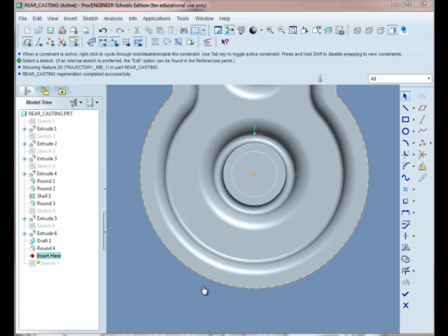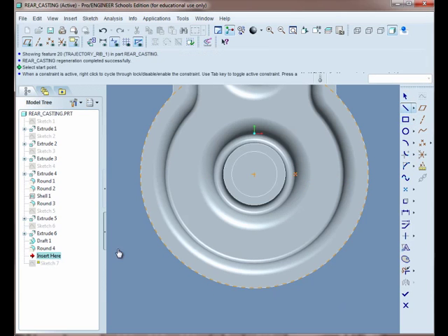Okay, so here we are going to draw a line across here, and you could infer to this point. Drag it across, middle click, and over here somewhere, and you don't have to make these extend all the way to the edges, just have short little lines. So we're going to use the rib tool. Click there, middle click. Now you see this one's going to be difficult because we can't really lock in to a point.